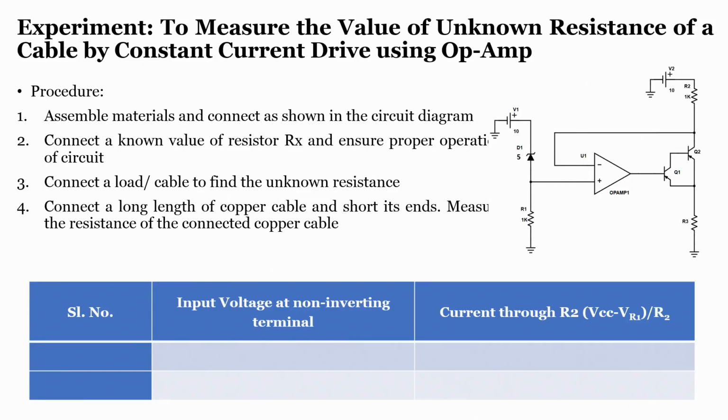So, actually in the experiment we have chosen LM336 of 5 volts. So, when we were solving, we considered the Zener diode voltage as 2.5, but for the experiment purpose, just to understand the next value, we have chosen the reference voltage as 5 volts. So, if it is 5 volts, let us consider what will be the current flow and everything.